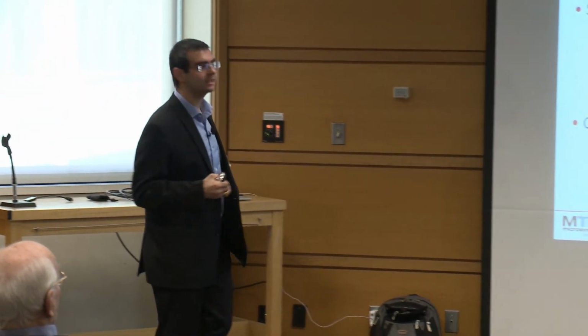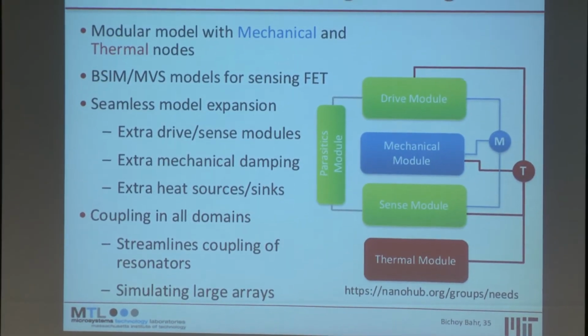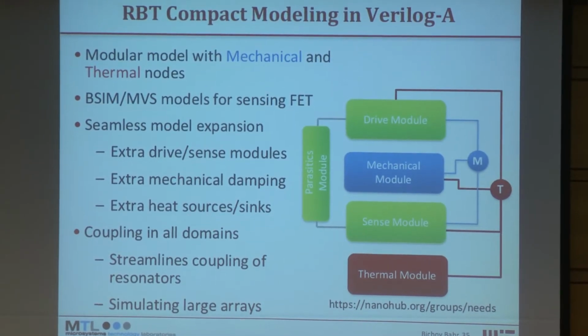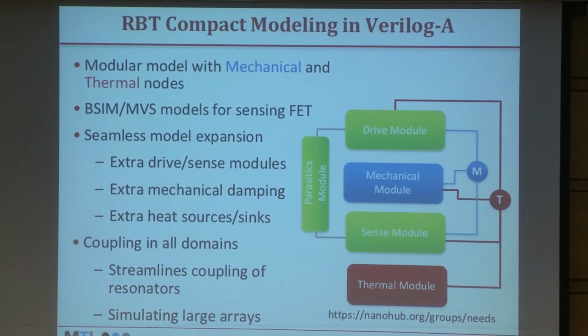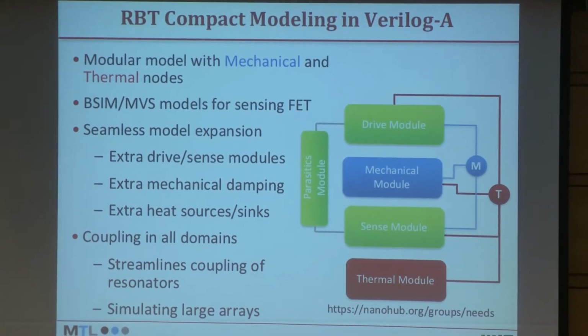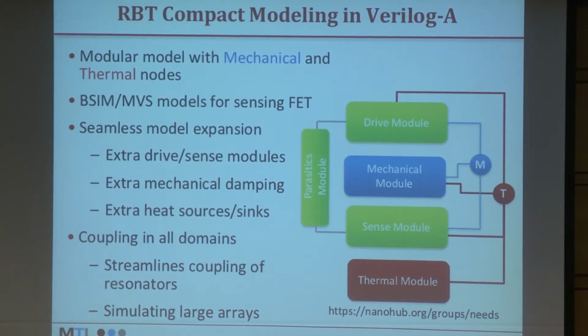So just a quick glance: in order for these devices to be useful for circuit designers, they need to have models that can fit in their CAD tools. And for this purpose, I worked on compact modeling in Verilog-A. Just to give you a quick high-level idea, this is how a model for such a thing is constructed. You have different modules: a module that simulates the resonance, a module that simulates the driving, and a module that simulates the sensing MOSFET. And of course, the module that simulates the sensing MOSFET has to be a complete MOSFET model. So yes, that's true.